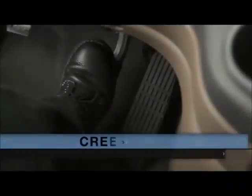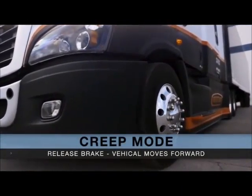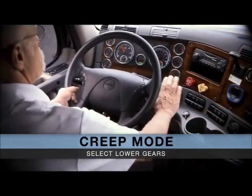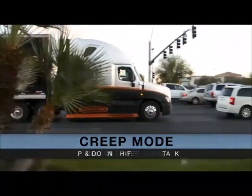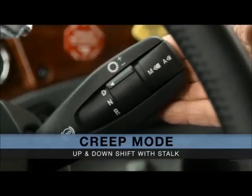Once the vehicle is stopped via the service brake, the vehicle will begin to creep again without any accelerator pedal input. You can also select a lower gear while in creep mode for sliding trailer tandems or in stop-and-go traffic, and the transmission can be upshifted or downshifted with the shifter stalk.